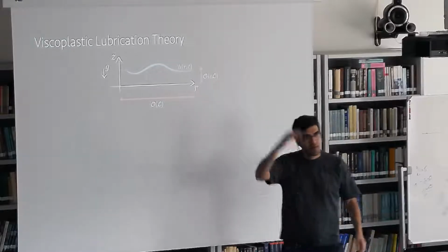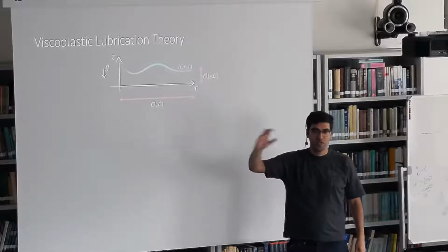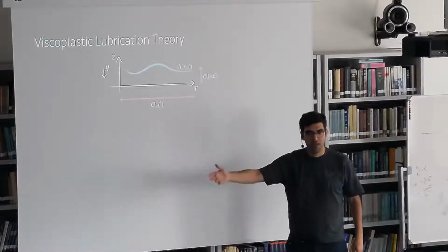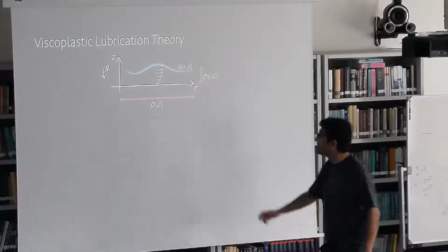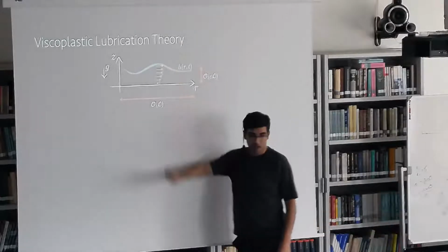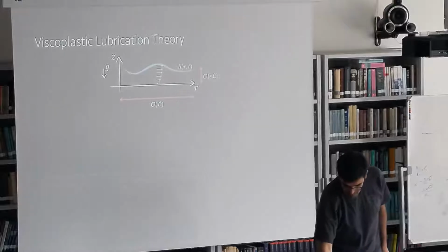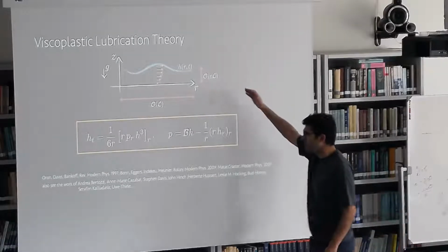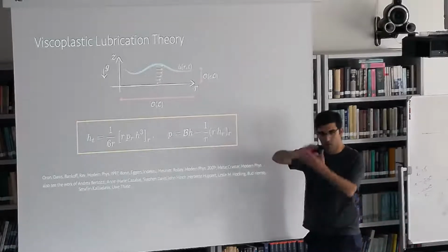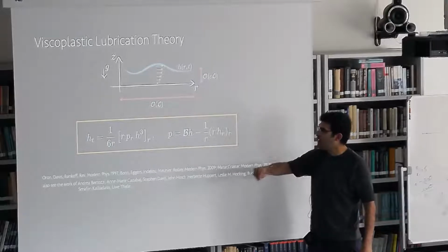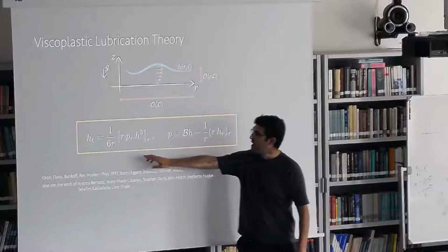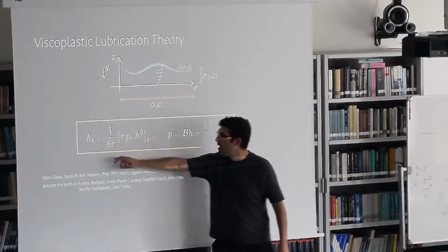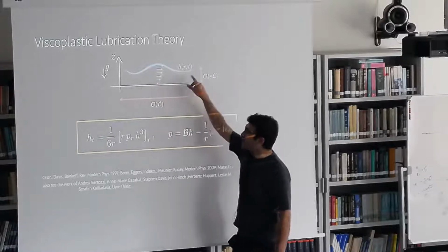Okay, so you start from Navier-Stokes, you change the stress tensor because you now have plastic deformation in it. I'll show you in a second. If this was Newtonian, you had the parabolic velocity field, and again, coming from Navier-Stokes, you do the height averaging as it's known, and I've cited a lot of papers here, and you get these differential equations, with h being the interface height.